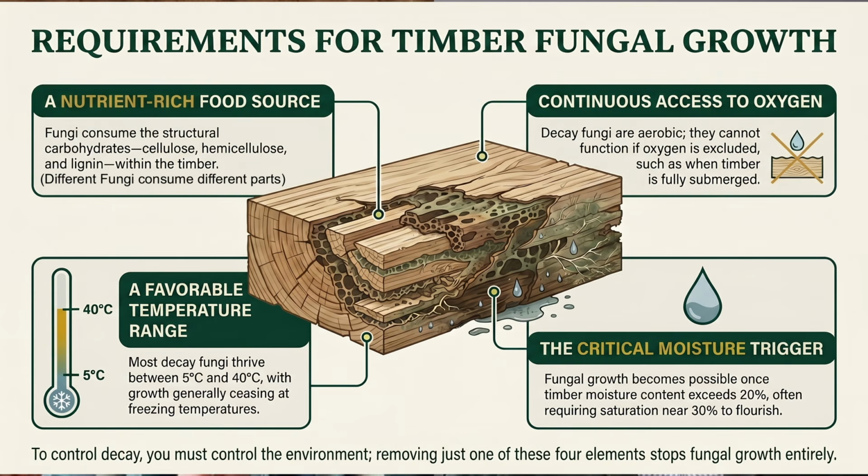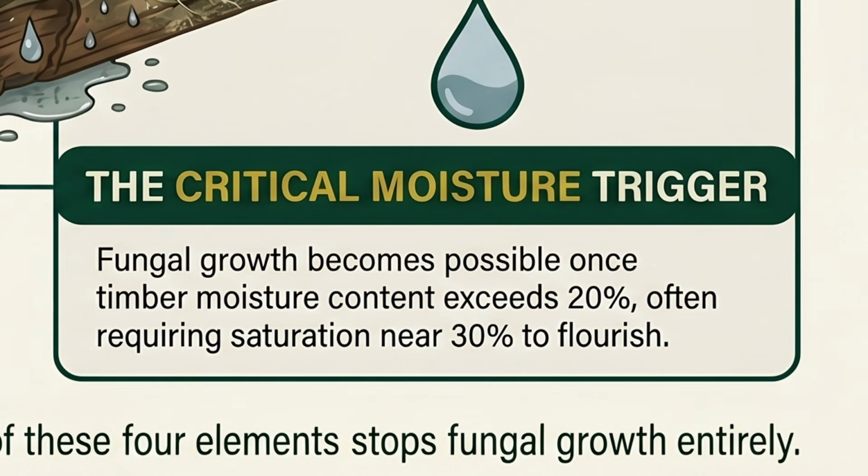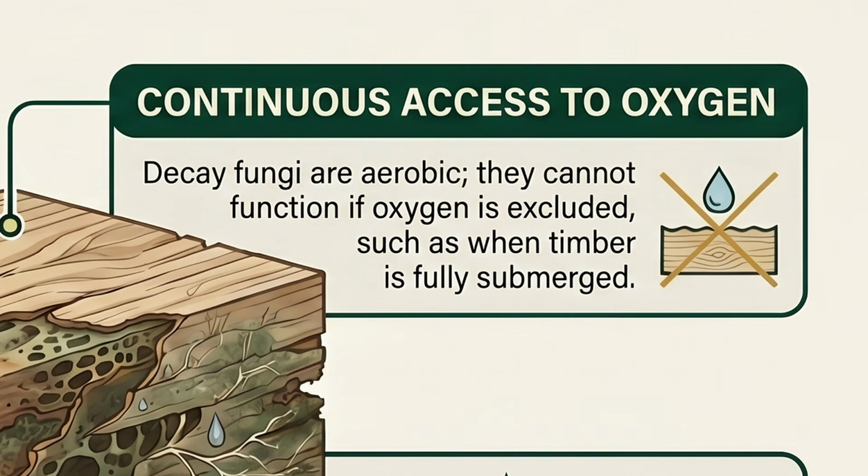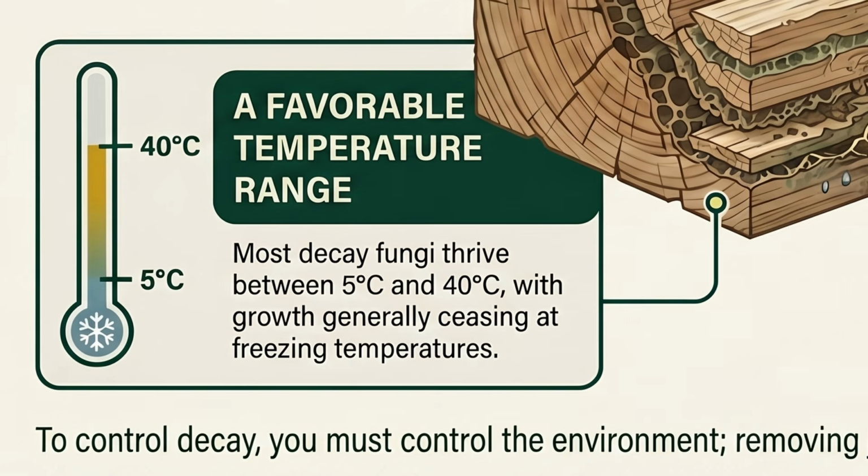Crucially, for fungal growth, we need four ingredients, and we've touched on a few of those already. So the four crucial ingredients are, you need the moisture. So the timber must be over roughly around 20% moisture content persistently, not just moisture above 20% then drying out. It's got to be persistent moisture above 20%. It needs oxygen. It needs a suitable temperature because it typically is between 5 degrees and 40 degrees. It doesn't work at below freezing. Like, we wouldn't function very well at that.